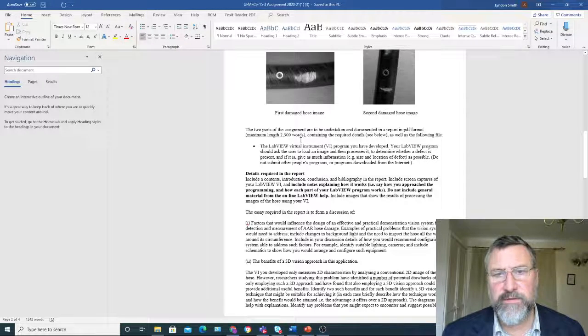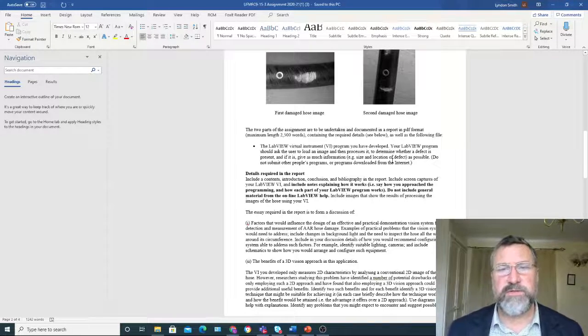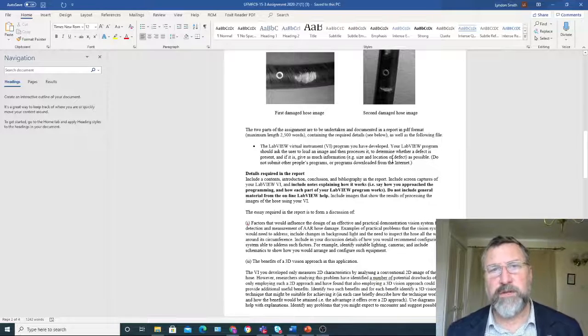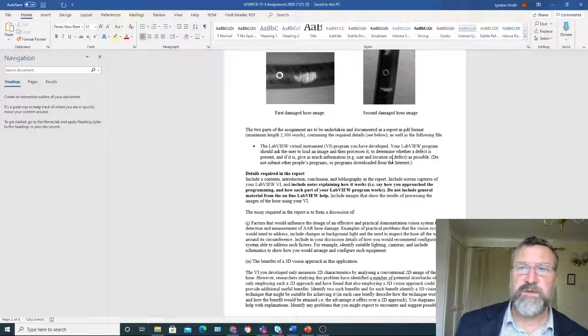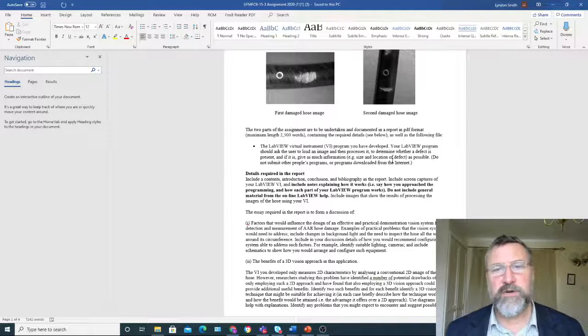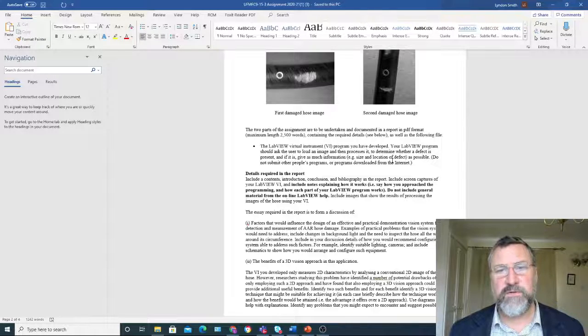And what we need to do is submit a report and this LabVIEW virtual instrument, of course. You want to make the LabVIEW instrument robust, get something working and keep it backed up in case problems occur. You can always go back to one that works. If you're trying to improve things, make it a little bit more slick, keep one that's working in the background all the time. And make it easy for the examiner, I would recommend.